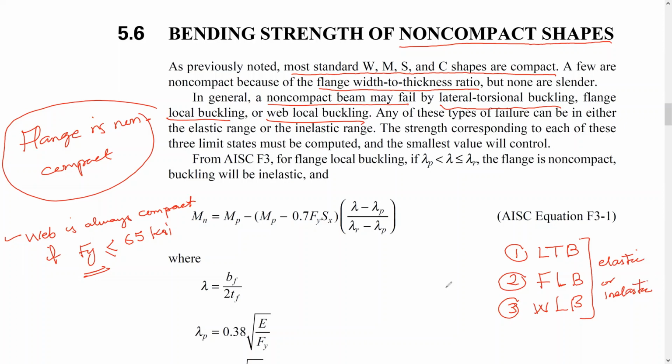So one more time, this is a stress-strain diagram, and let's say this is for a ductile steel. There is a proportional limit here. If one of these bucklings happens here, that means it's elastic. If it happens beyond this point, that means it's inelastic or plastic buckling.